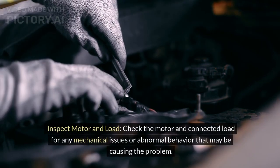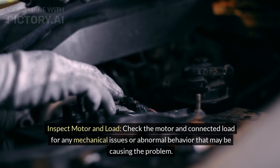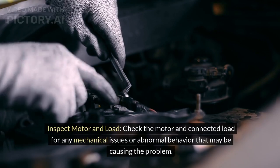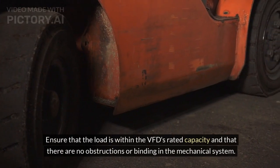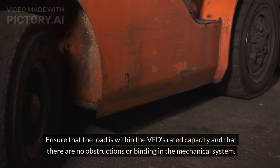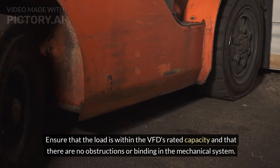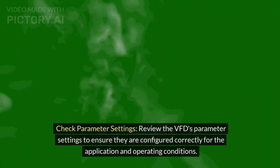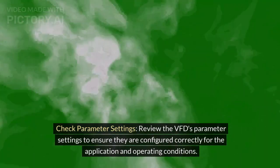Inspect motor and load. Check the motor and connected load for any mechanical issues or abnormal behavior that may be causing the problem. Ensure that the load is within the VFD's rated capacity and that there are no obstructions or binding in the mechanical system. Check parameter settings. Review the VFD's parameter settings to ensure they are configured correctly for the application and operating conditions.